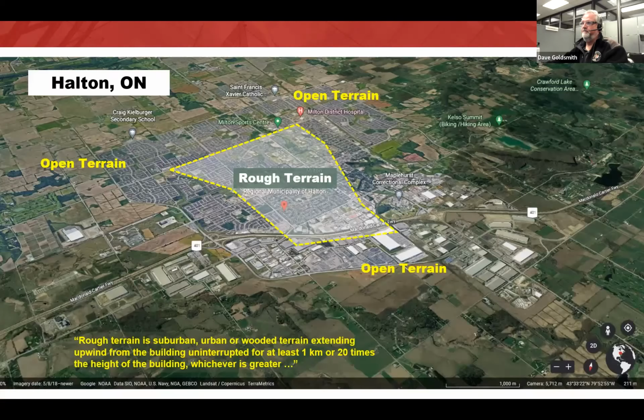Yes, and I think in Canada, because of our history of using A440-00, under that standard there was a maximum requirement for housing in small buildings, and it was A3, B3, C3. There was no requirement, if you're doing housing small buildings, to design for any higher than that under the old standard. So people just designed their windows to have a minimum performance of A3, B3, C3, and then it was fire and forget. And so those A3, B3, C3 levels are still in the background, kind of the standardized basis of design for typical windows in Canada.